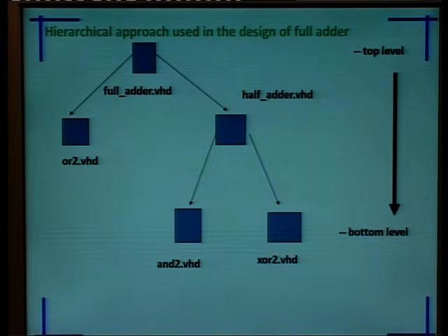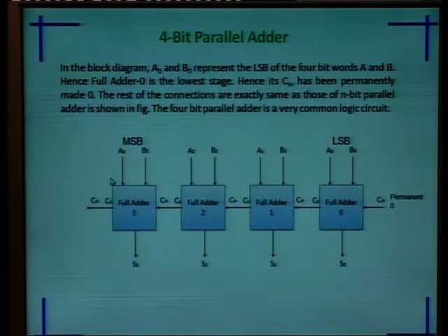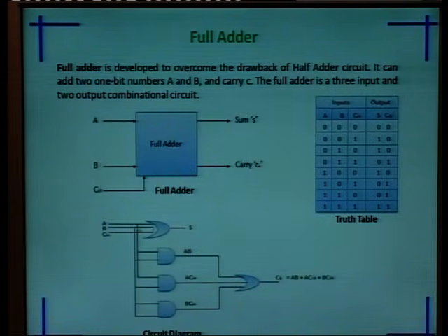Next is the hierarchical approach used in designing the full adder. In the hierarchical design approach, at the system level we know what we have to design, meaning our specification is to design a full adder. We can break down that system into small modules, meaning we can design half adders, and there may be modules for AND, XOR, as we require in this circuit diagram of the full adder.